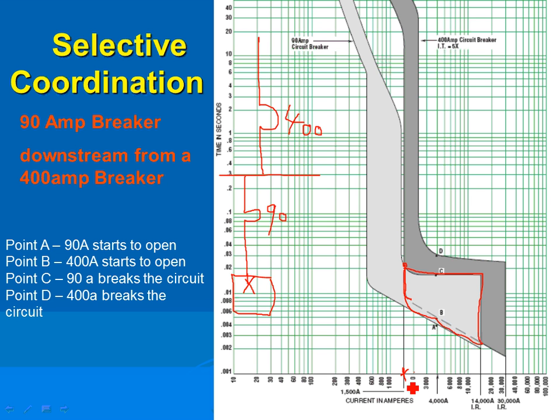But to get the 1500 though, two things could happen in real life. You almost have that fixture and that panel that feeds the fixture have to be right directly next to the service, very high short circuit, closer to the service. Or you went to phase A and phase B in a J box and you tied them together on this three-phase equipment and you flip the switch.